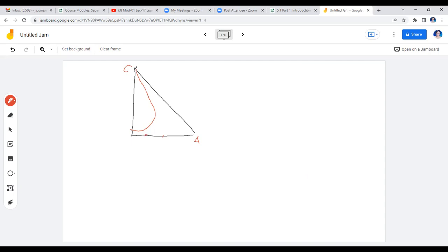So this is your L sub O. That's where your L sub O is. Now your solvent is 100% isopropyl ether, so it should be here, just like what I've explained a while ago. It should be on the apex of the triangle because this location signifies 100% C. This is 0. Okay, now this is your V sub n plus 1.